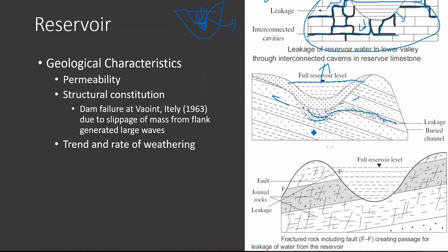So that kind of paleo channel is very common in the case of a river system, where some channels will be there, and may be filled with the sediments of the river, but need to be identified. So this is a real story of one dam construction in India itself. They faced this issue, this paleo channel, and they detected it when they started storing the water, and there are a number of treatments possible for this. It may need to be plugged all the area. It has to be completely detached from the other surrounding area. So, but it is an expensive affair. It is not easy as was seen. Or it may be grouted completely.